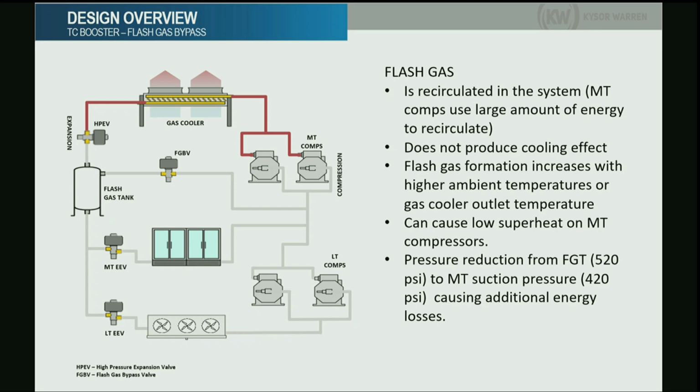So when we enter the high pressure valve, which is in reality an expansion valve, it reduces the pressure of that fluid. When it reduces the pressure, at the same time it reduces the temperature. So what happens is, at the outlet of that high pressure valve, we will have a mixture between vapor and liquid, okay? That is basically when you will see the change of state from that vapor going partially liquid and partially remaining vapor. You don't have a full condensation in that case.